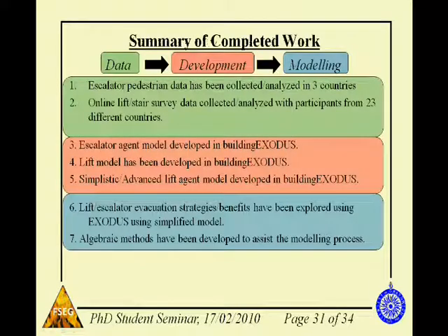To summarise the completed work, I've collected human factors data on how people would behave on and around escalators and lifts via video footage and online survey data. We've quantified various types of human behaviour on these devices, and we've developed models within Building Exodus to represent the types of behaviour.